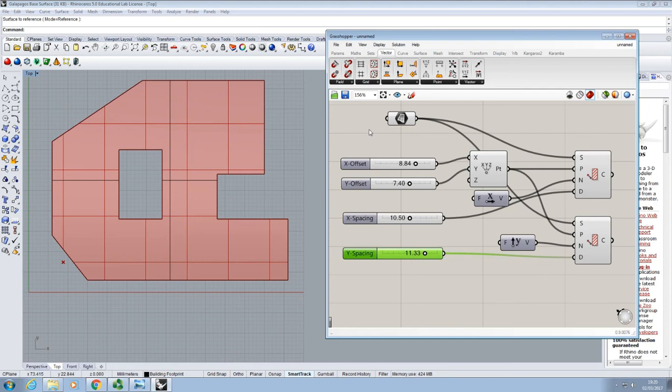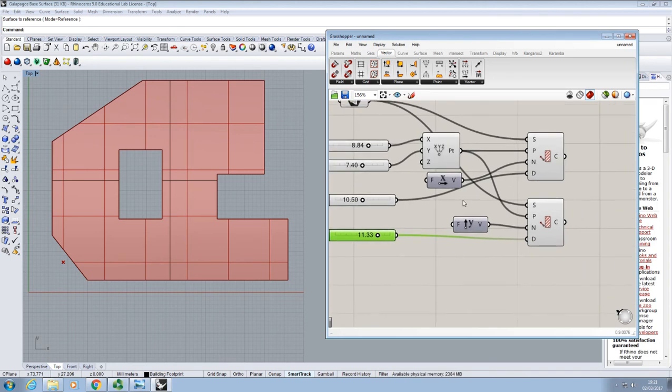So this gives us our grid lines on our floor plate. Now what we want to do is to, based on this grid, generate our column positions. So we're going to work in 2D, so we're just going to use points to represent our column positions. And we're actually going to create columns based on 3 different rules here. So the first rule that we're going to use is the fairly obvious one. We're going to create points to represent columns at the intersections between these 2 sets of grid lines. So where these 2 sets of grid lines cross each other, we'll put a column there. It's what you normally do in a column grid.